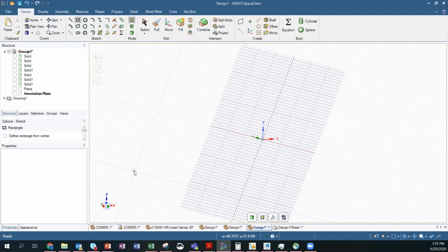Say PBT is $1 or $1.5 a pound. Nylon would be $4 a pound. It's like twice the cost or more, but still, a pound is $4. If you're making few parts, it doesn't make a big difference. And PBT is easier to manufacture because you have to melt the plastic and flow it into this design.